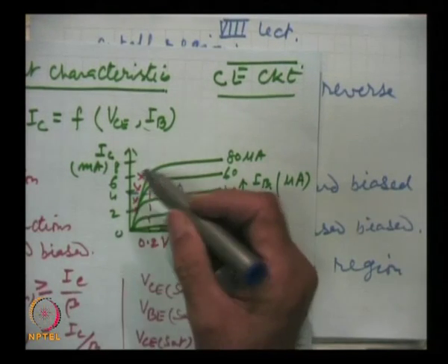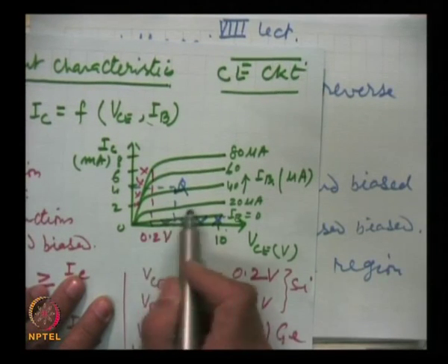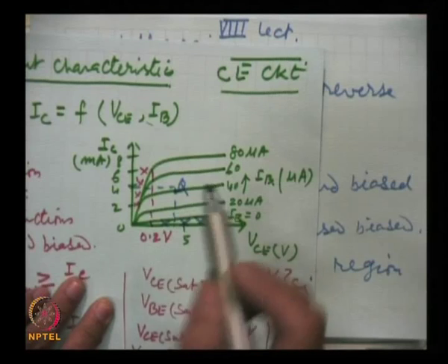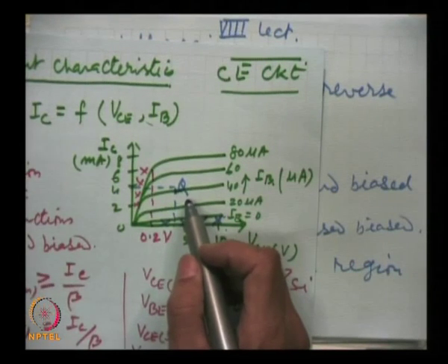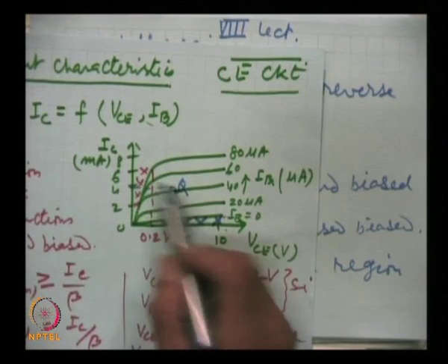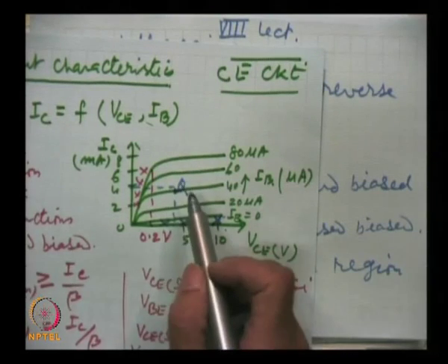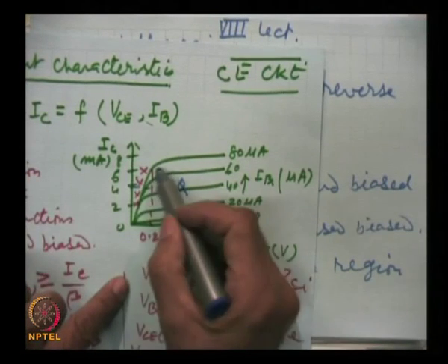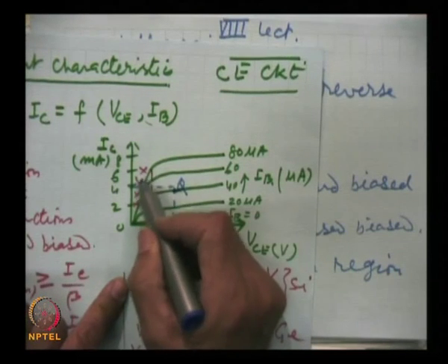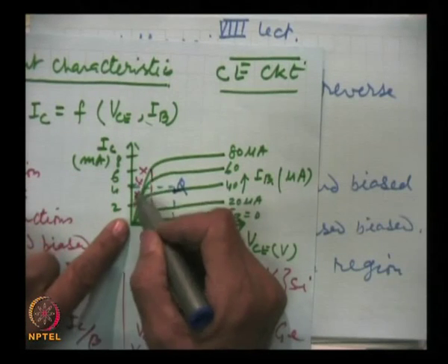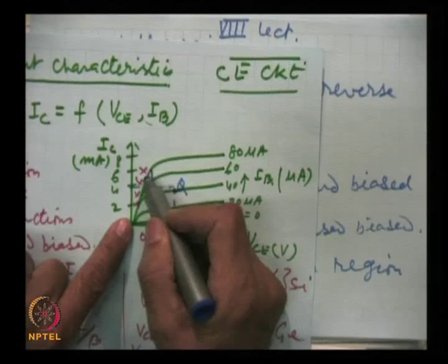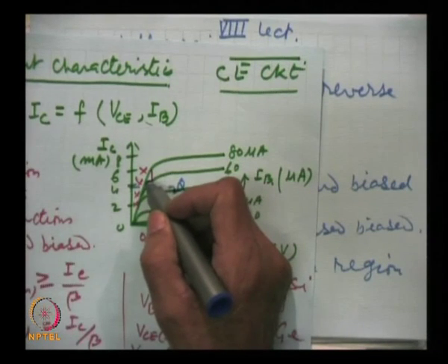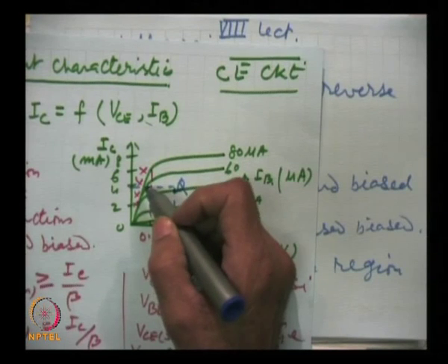Now, when we apply the AC signal, the input current will vary and correspondingly the output current will vary. In no part of the cycle, when the AC is superimposed over this DC operating point, should the signal go beyond the active region on either side. That means it should remain within this prescribed region, because if by wrong choice it touches or comes into the saturation region, the output will be distorted, because that much part will not appear in the output. So the output will be a distorted signal, which we have to avoid.